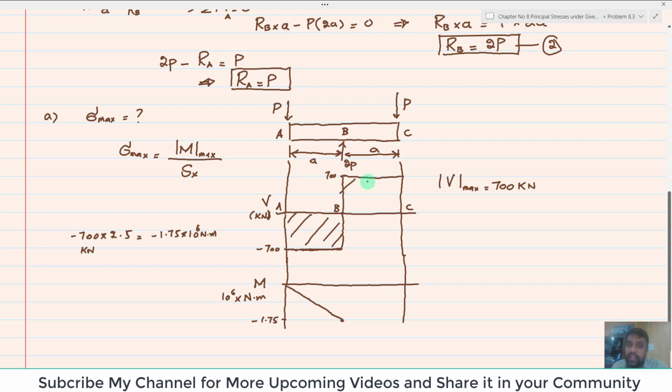Similarly, from B to C, again you can see this is the area and it is the same, 700 multiplied by this A distance, which is 2.5, and it will again give you plus 1.75. So minus 1.75 plus 1.75 will give you 0. And since this is a 0-degree line and positive, your slope will be upward and it goes to 0. So you can see the maximum bending moment is equal to 1.75 into 10 raised to power 6 Newton meter, and this is 700 into 10 raised to power 3 Newton.